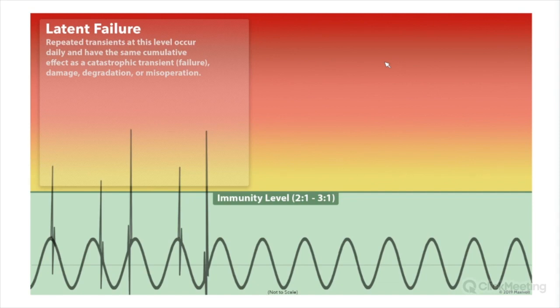Yeah, that's good. Okay. Again, that voltage can be AC or DC. So whatever your system voltage rating is, let's say it's a 24 volt control system, anything that exceeds twice the rating of 24 volts, 48 volts, the system is tolerant up to 48 volts. As soon as I start breaking above 48 volts for DC, that's when I start seeing component failures and overheating and degradation.